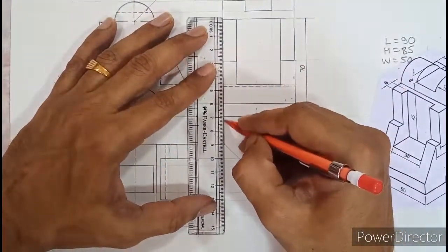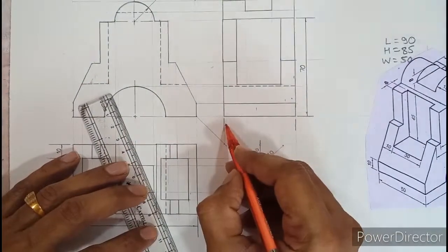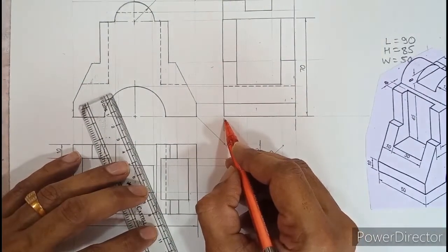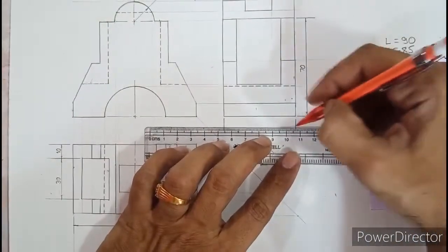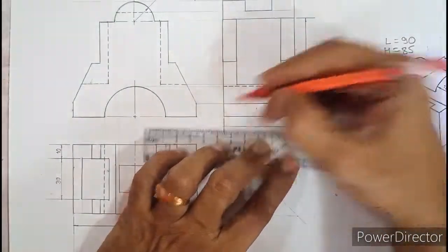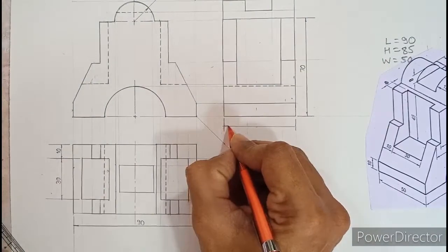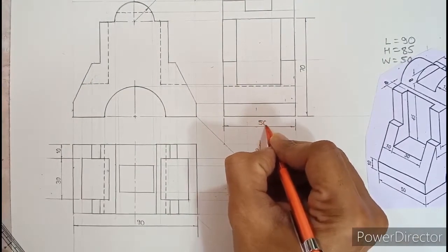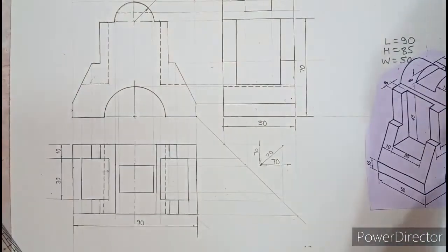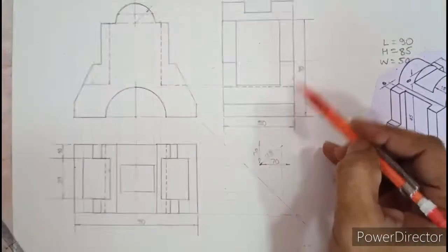So don't forget to leave a gap of 2 millimeter, and you have to show a medium dark extension line over the projection line that you have drawn before. And this width is 50 millimeter, so we are showing 50 over here. So you can see that length, width and height are shown, and if you count the dimensions, 1 2 3